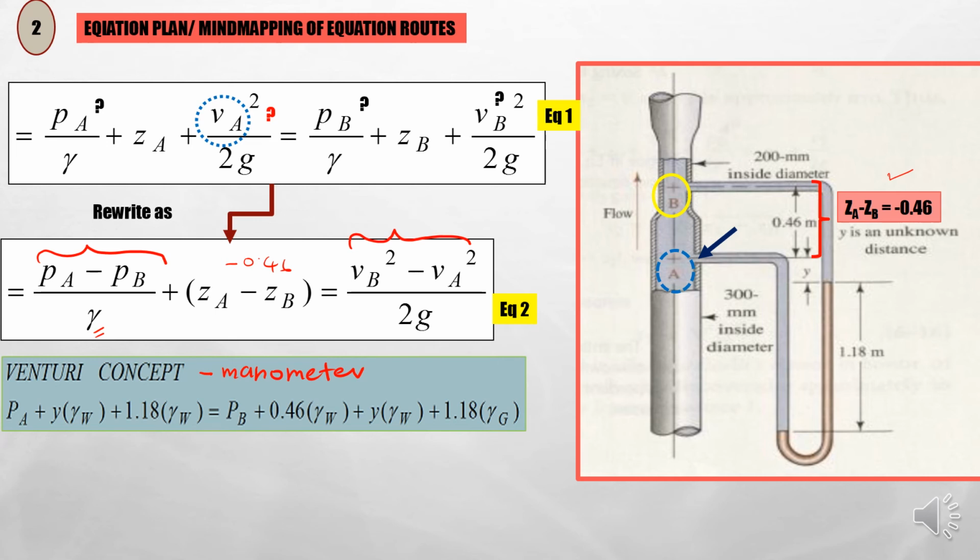So remember that in order to use the manometer, we have to divide the U-tube section into a left and a right section. Then we find the level which is the same on both sides. This is the level that I intend to use. Let's say this is level P and level Q. Definitely the level here is the same, so pressure at P will equal pressure at Q.